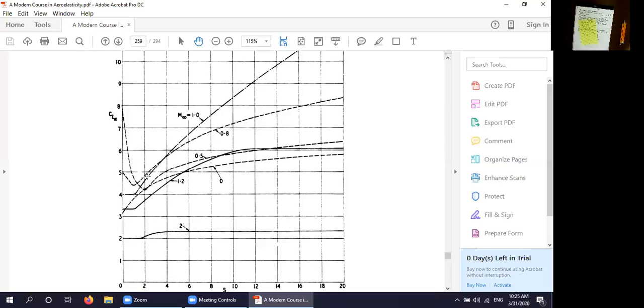Exactly. Because historically, if you go back to the beginning of unsteady aerodynamic theory, people thought that solving the incompressible flow model would be easier than the compressible flow model. In some respects, that is true, but in other respects, it's not. It's true in the following sense. If you go back to the wave equation that we're trying to use as our model, if I non-dimensionalize that equation and set the Mach number to 0, that wave equation reduces to the Laplace equation.